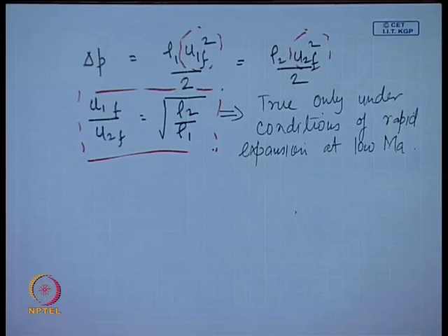We had first started with the two fluid model. We wrote down the equation of continuity, we wrote down the equation of momentum for the two phases, then we combined them in several ways. From the combined equation, we found out the condition of choking. After finding the condition of choking, we found that the results can be misleading under certain conditions, particularly because del alpha del p is usually derived for low to moderate pressures where friction dominates inertia.